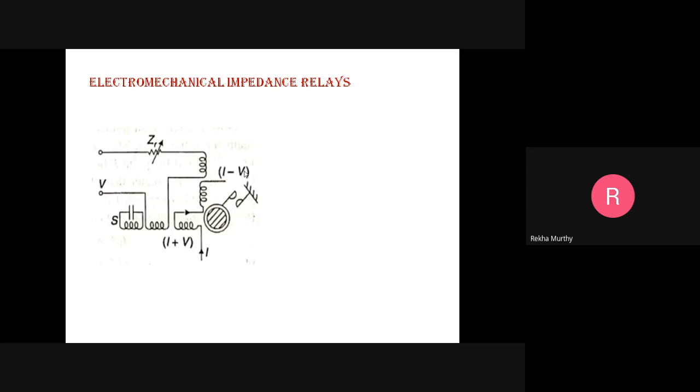So the polarizing quantity produces one of the fluxes. In case of the phase comparator, it provides the reference for the phase angle measurements. So this is what about the electromechanical relays, by which you are going to realize it as an impedance relay.